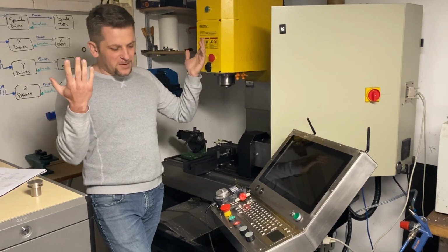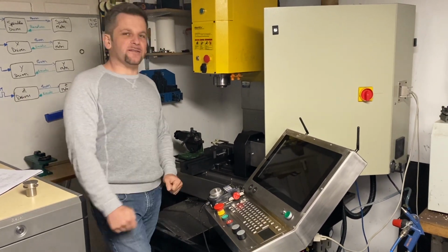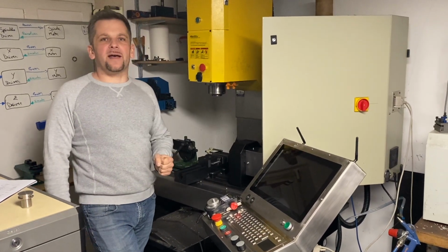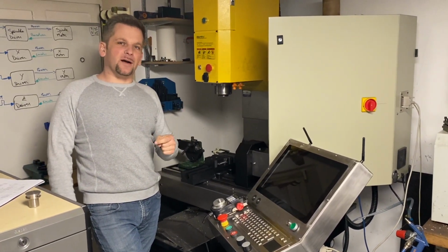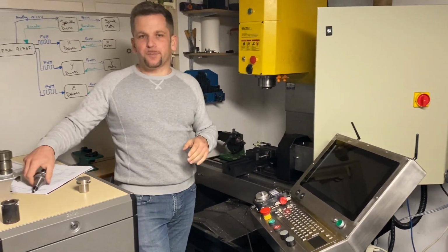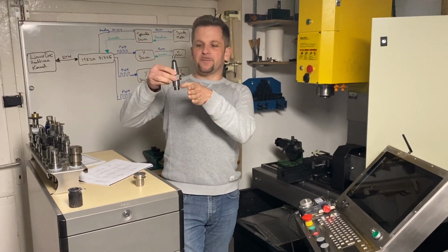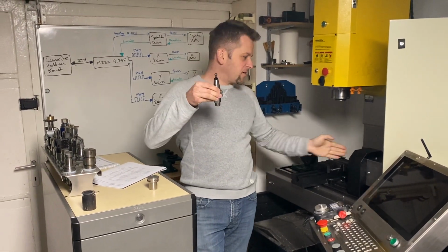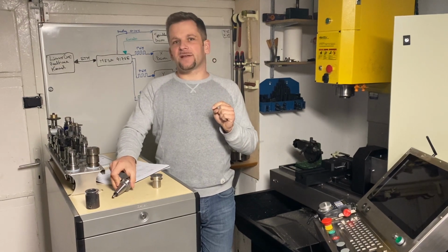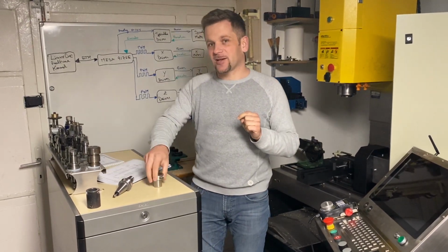And me, stupid enough, I did not press the stop button. I opened this to look what's happening, why it's not moving, and at that time, due to a LinuxCNC bug, it started homing on X and Y. So that was the point when it bumped the tool sideways into the fourth axis. That should never happen, and that's the issue that I'm going to talk about next.